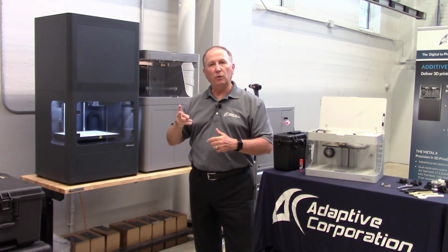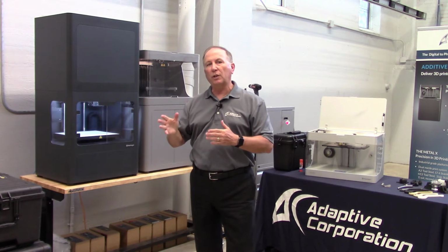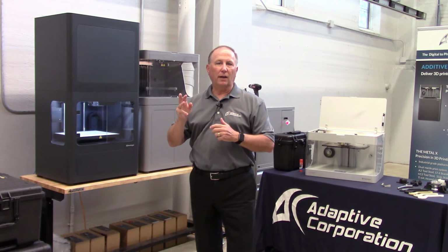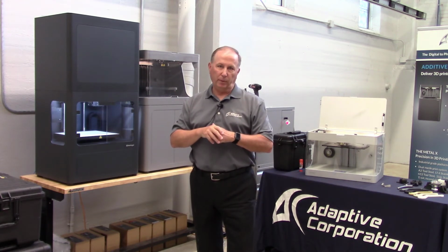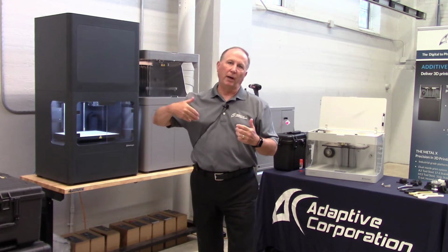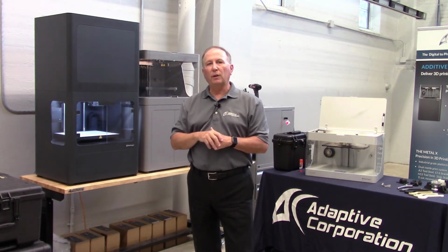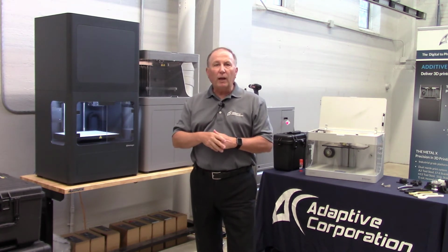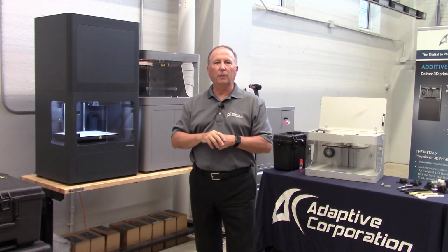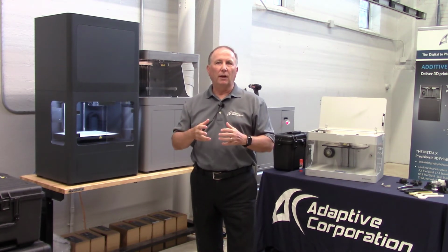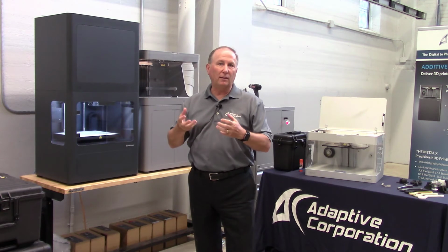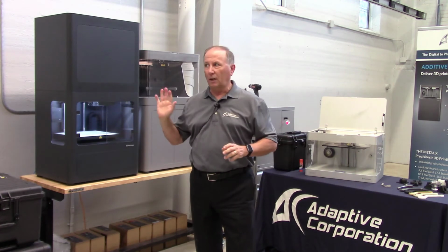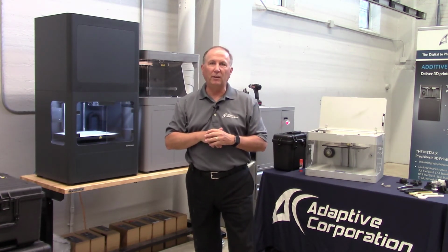That's step 1. Step 2 is that we wash the part. By washing the part, we're removing the first binder, that being the wax. And then the third step is sintering the part. When we sinter the part, which is about a 24-hour cycle, the sintering process removes the second binder, which is basically a polymer. After we have removed the second binder out of the metal part, the part has been fused into a solid 97% dense part that meets our material specs. So we're going to talk about that process here in a little bit more detail.